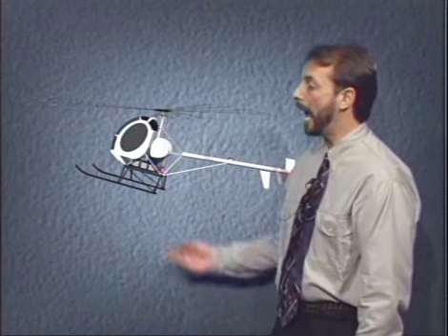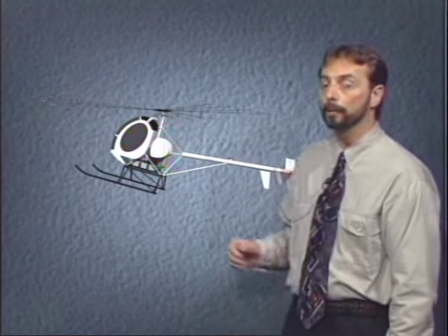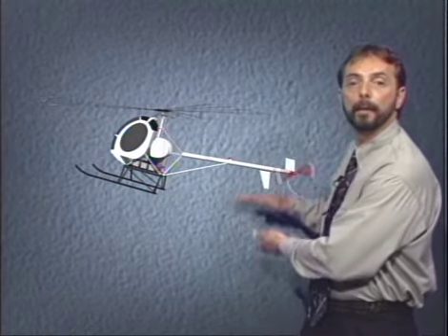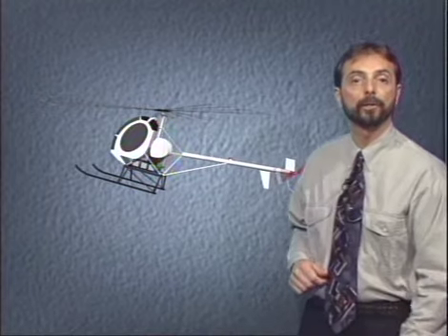How you load the helicopter will affect its flying characteristics. If you load the helicopter so that the CG is located aft of the allowable CG limit, it'll be difficult, if not impossible, to lower the nose if it should pitch up. If you think about it, this makes sense. There's too much weight in the back, causing a tail-low attitude. There won't be sufficient forward cyclic displacement available to push the nose down. This could be especially problematic in gusty winds in high-speed flight where it's necessary to maintain a nose-low attitude.